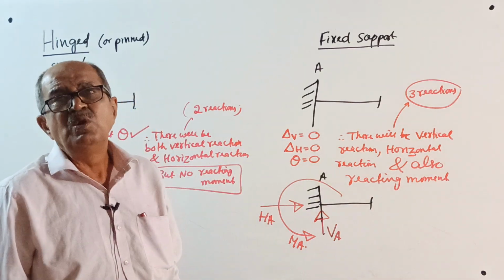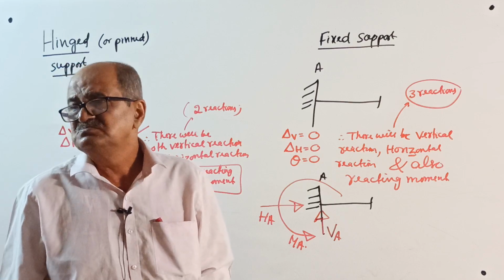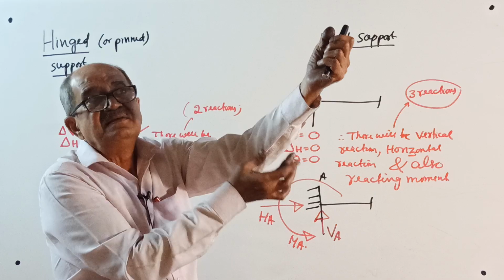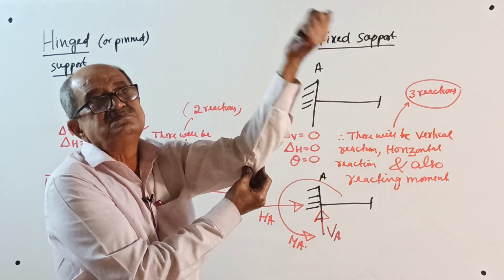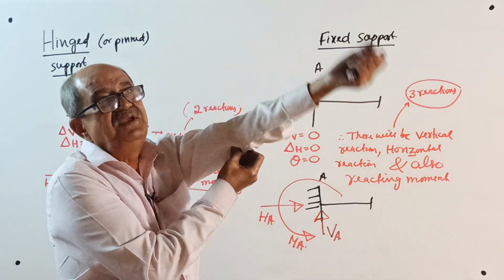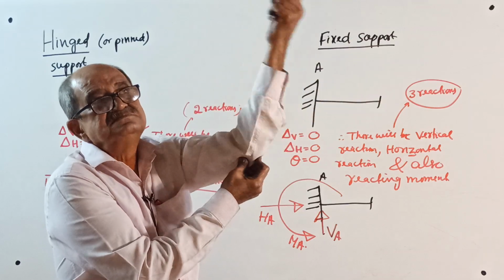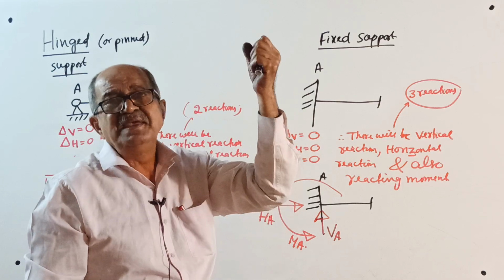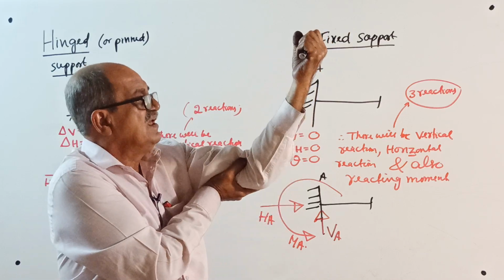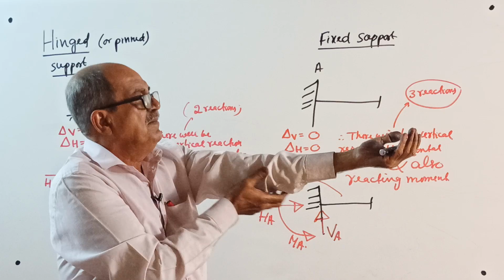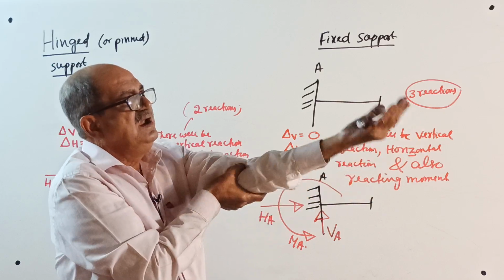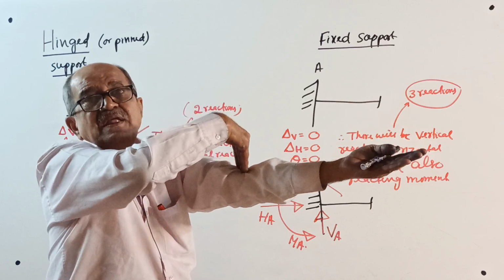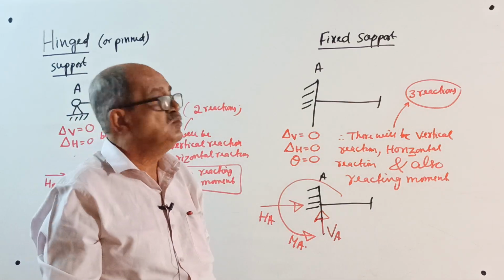So we can give a lot of examples for pin support. Even our hand, this junction is a pin support. See here, it can rotate, but it cannot move horizontally. This movement is something else, don't worry. If I firmly fix here and apply a vertical load, it will rotate. But if I press down, it will not move. If I pull, it will not move.